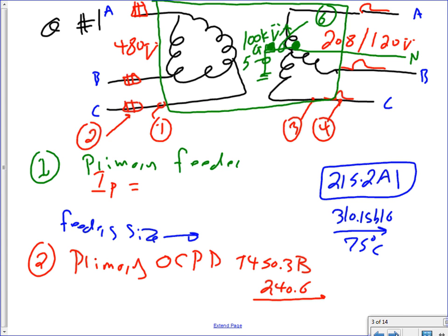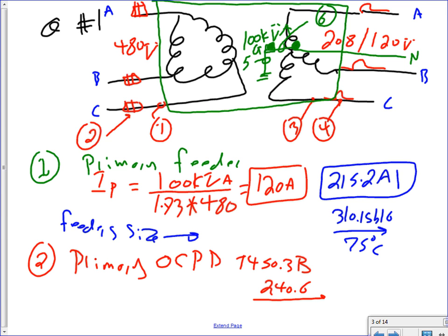I will remind you the amount of power that this transformer can transfer, on the primary and the secondary, is 100 kVA. So if you take the primary, I'm going to use red here, 100 kVA, not kW, divided by 1.73 — any suggestion why 1.73? 3-phase, thank you. And what's the voltage on the primary side? 480. Now we're calculating I primary of the transformer. Anybody can come up with other than 120? 120 amps. So that's my current, 120 amps.